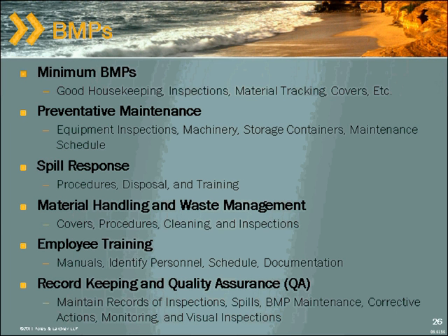And of course, the record keeping and QA: all of these inspections, the training, any spills, BMPs, type of BMPs, maintenance, all needs to be very well documented, and those records need to be kept very well within the SWPPP for multiple reasons. And this is the first permit in which I think we use the term quality assurance, and we mean it. Okay? I think it is different than previous permits where we talked about quality assurance at the laboratory level.